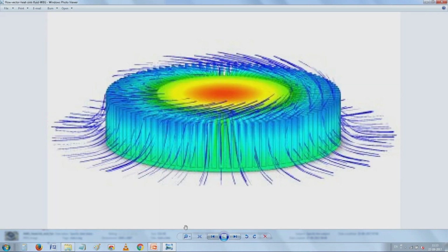So, you have a circular heat sink with radial fins. They are not just radial, they are strictly not radial. If you see they have all been made sort of halfway between tangential and radial, because when the air from the fan spins, it seems to also take it into a particular thing. So, it makes sense to make things like that.